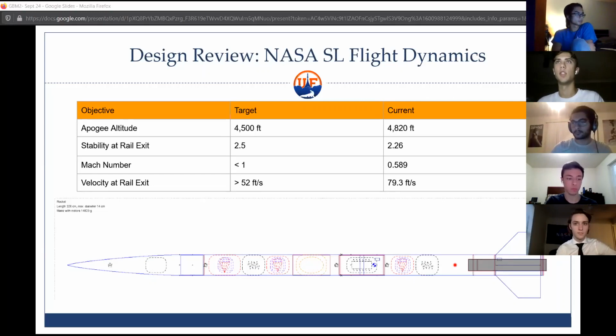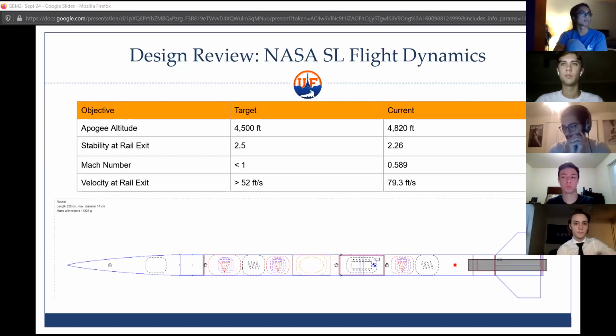You might want to consider putting the legs closer to an area where it could get out, because I'm not sure of your mass estimates yet, but 3 or 4 servo motors in it should be pretty hefty. 4 servos, right? Yeah, it's 4 pounds. So that's going to be really hard to push out the tube. I'm not sure of your exact ejection setup. Is it shooting out next to the avionics bay, or the other direction, around the nose cone?